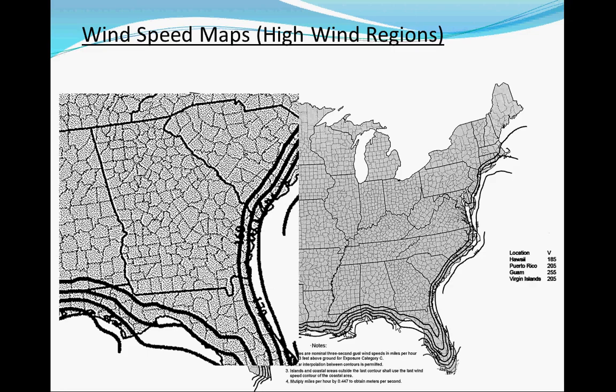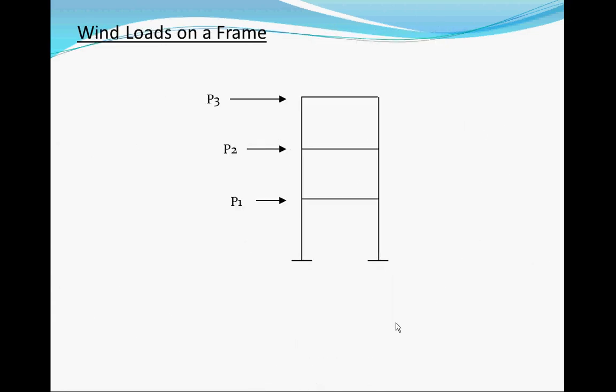There's actually a presentation from Shane, I think, so I'll just combine some of these things. So wind loads on the frame. For what you guys will see, typically you'll see point loads at the node, and then you just apply your wind load, and the wind loads typically go higher when you go up the building. But for frame analysis, we typically lump it at each height. You could put it in either as a distributed load or at each node, either way how you apply it, but it's just higher when you go up higher.